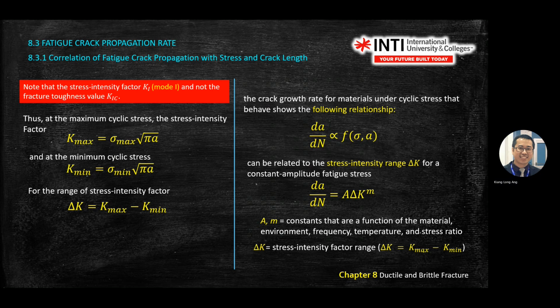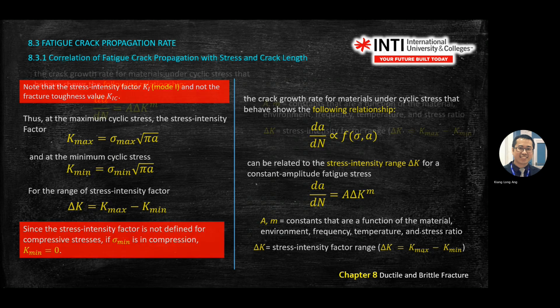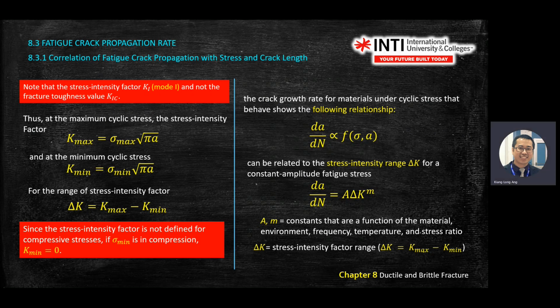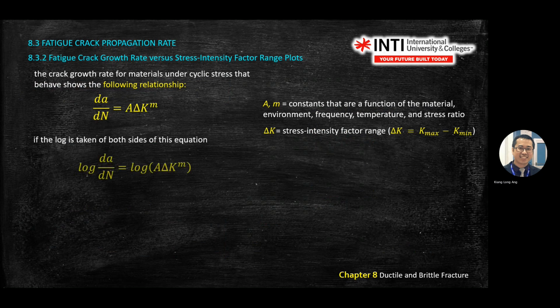Okay. And recall that we have lots of mode of failure. We are now talking about mode 1. So for the K here, it is not defined for compressive stress. So if your minimum is compression, your K minimum, you put 0. Okay. The rest you read.